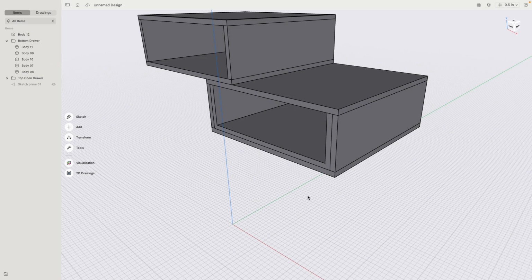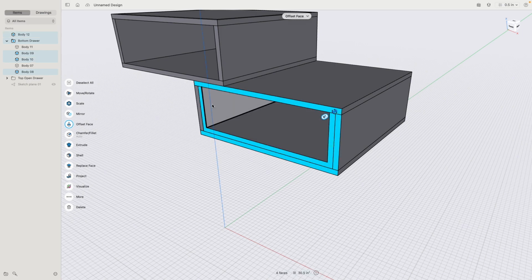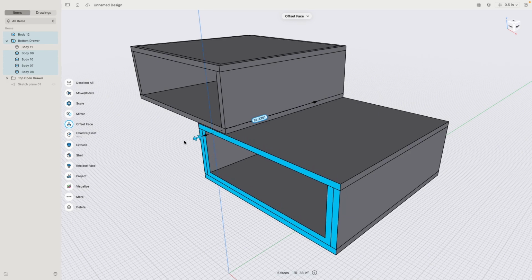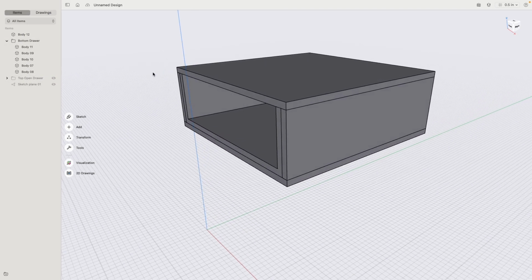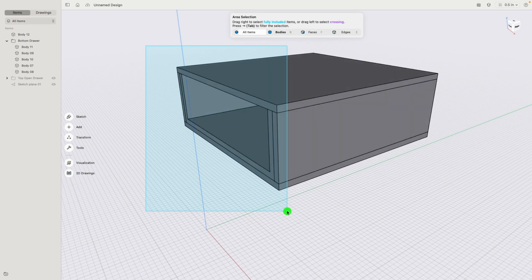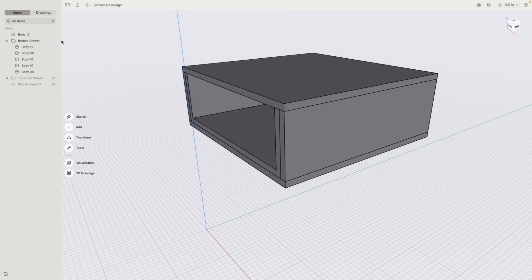Let's show this part again. When we would like to have also a drawer face, I would like to stick over a little bit. So these faces, which I'm selecting here right now, we can select and move backwards by 1/2 inch. I would like to show you something. This top open drawer I hide, because now I can very easily draw a selection over this front, and then via tab I decide what am I selecting. I select it from the left to the right, so everything that's inside the selection will be selected, just these faces, and then minus 0.5. And that moved it all back.